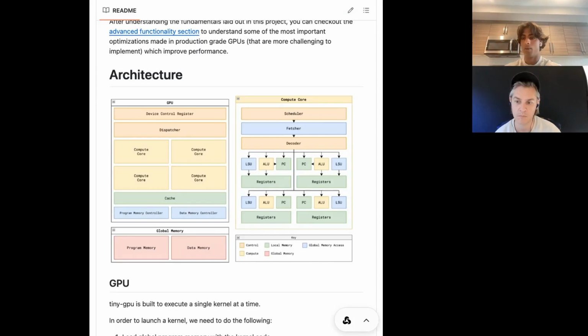They just released their Blackwell. Obviously they've been boosting their FLOPS in many other ways, but Blackwell now has smaller floating point numbers because ML doesn't really need gigantic floating point numbers, unlike graphics. By doing that, they massively boosted the FLOPS, and it is actually meaningfully faster for the use cases that it's relevant to. So it's the exact same implication. If you use 2-bit, 1.58-bit values, the FLOPS is going to go up like crazy.